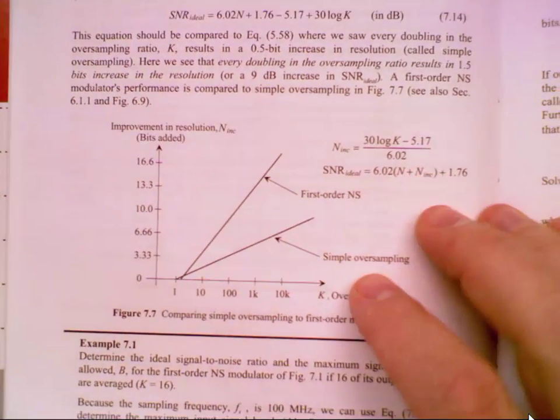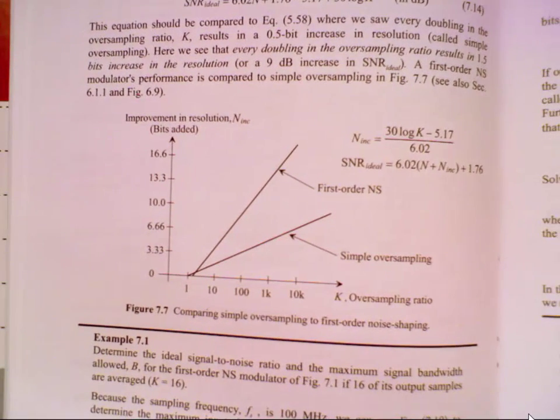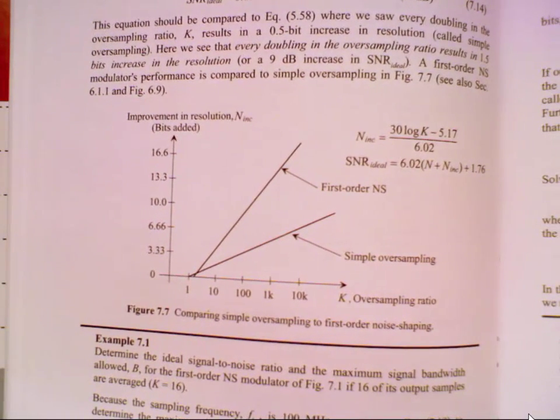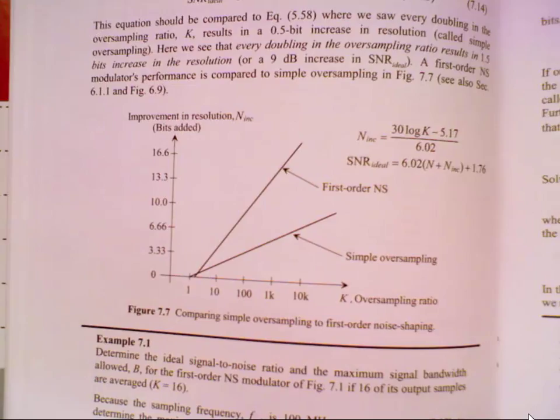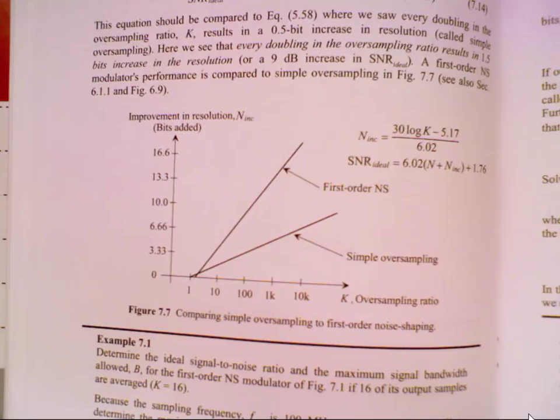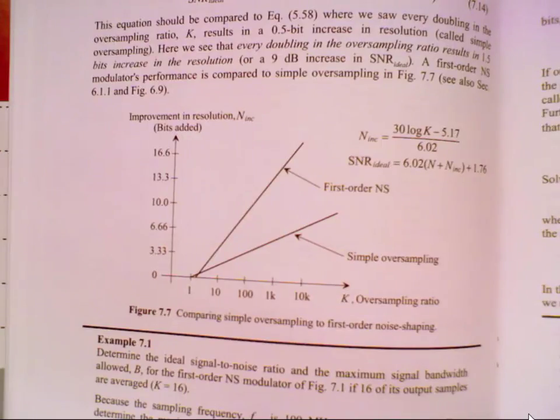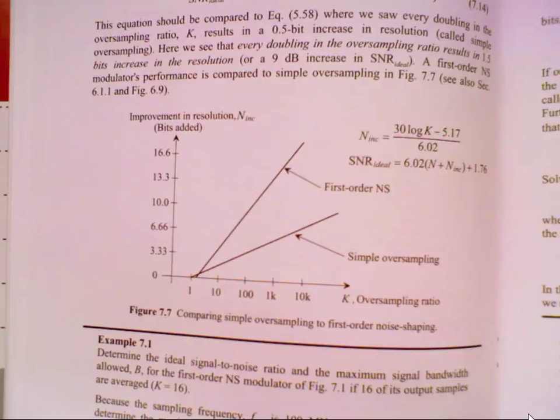So I have not funny, but I have a story about this. So you know flash memory? Did I tell you this story? So back in the mid-2000s or whatever, flash memory was really taking off, as before they had the thumb drives and all that. So I developed these techniques for doing delta sigma modulation for sensing flash memory. Nowadays, well, and it's been like this forever, they basically charge the bit line and then they turn the flash cell on, and then how long it takes the flash cell to discharge the bit line corresponds to the data value. So what I said was, well, it'd be great if you could sense indefinitely and use delta sigma techniques.